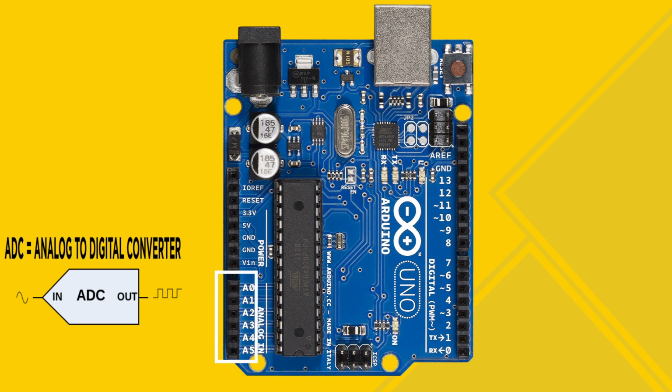So this is the main feature of these 6 pins. They can work as outputs as well, but generally only if you need to do small variations on those outputs you use them, but normally they're used as inputs. But we'll see in the future a couple of examples and applications where you use the analog pins either as inputs or outputs.